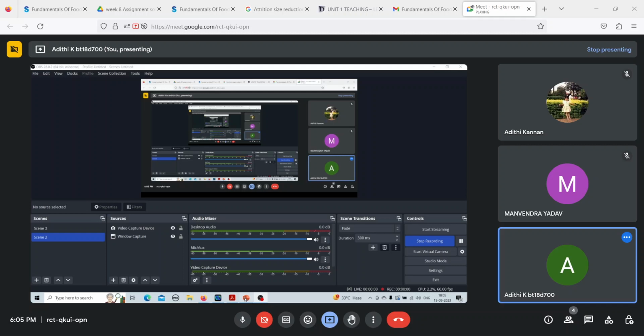Since Rittinger's law says that the energy consumption is directly proportional to the surface area, it applies only when you break down the particle and it has a new surface area. That is when you can apply Rittinger's law. And this holds for fine grinding, where the increase in surface area per unit mass is large. The answer here is option B.